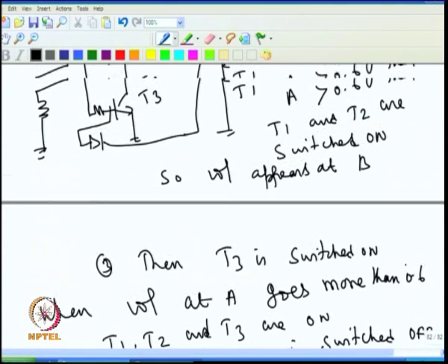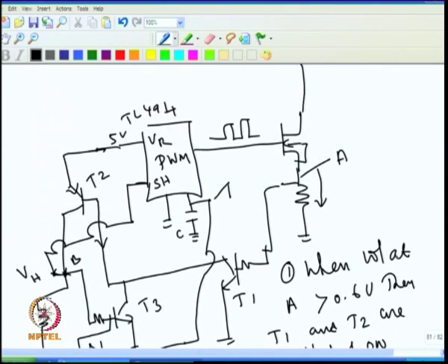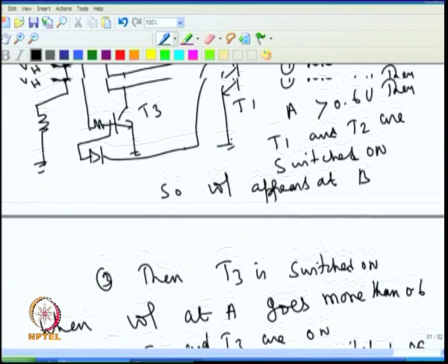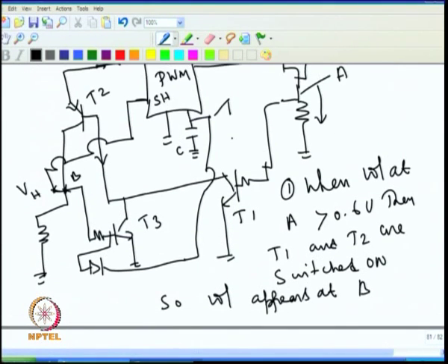So, when the voltage across the capacitor C drops to 0, automatically this voltage decreases, and then this transistor stops conducting, and B also stops conducting, and B becomes 0, and now the next pulse can appear. So, this way it can act as a latch. That means once the pulse voltage goes high, it can be latched, and the latch function can be easily obtained using this process.